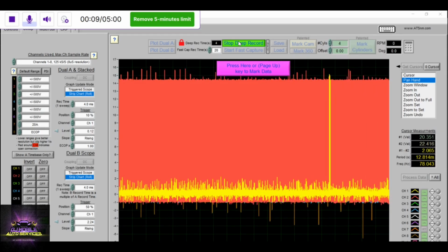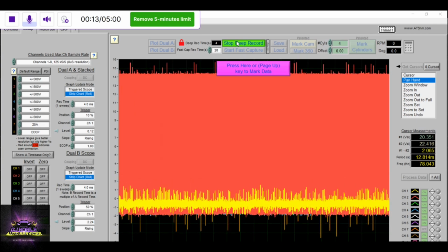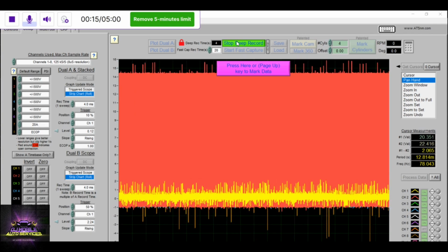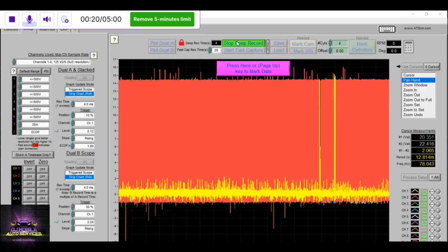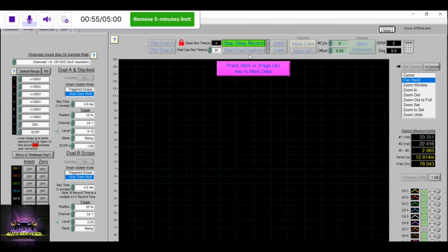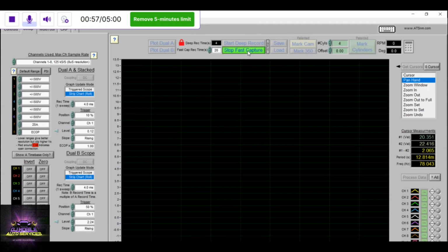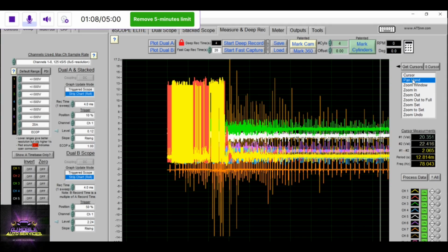As I stated earlier, the red and yellow traces are the DC motor within the throttle. The green and blue are 5-volt ref and signal ground. The white and purple are TP1 and TP2, and both values have to add up to like 5 volts and crisscross each other when you step on the accelerator, especially on this vehicle. I have the brown trace there for the ignition coil secondary signal, just to ensure that the coil is not hitting the ECU. I just want to monitor that.